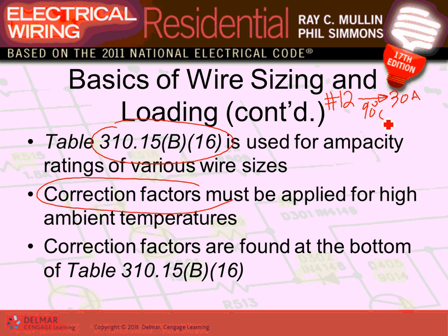When I teach lighting guys on ampacity, I say, enemy number 1 of electricity is what? Heat. You take a conductor like number 14, you can make this conductor carry 100 amps if you can cool it properly. Why is heat an issue? Heat will melt the insulation, melt the copper. So imagine having conduits with insulation being melted and copper being melted inside the insulation and shorted and so forth. Is that what you want in a power system?